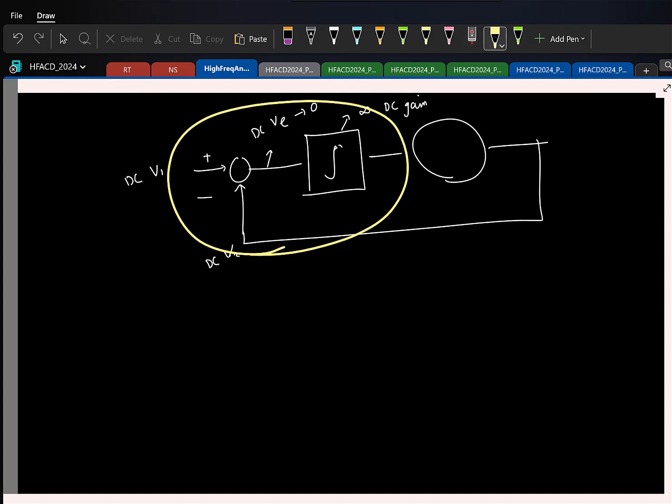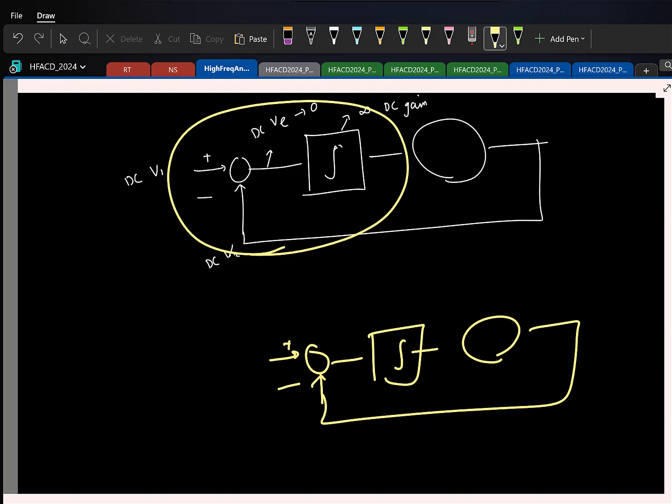I mean, not go there, but gradient descent, everything kind of depends on the fact that you have an integrator and you have something added here. And the fact that the integrator has infinite DC gain is what will make this go to 0. So these two will become equal. Because there you kind of repeatedly add, repeated addition is integration, right? So yeah, the integrator is one powerful thing that is kind of making our world stable. Cool.